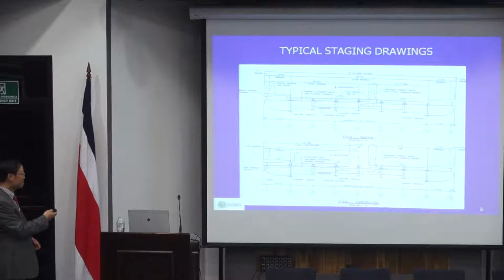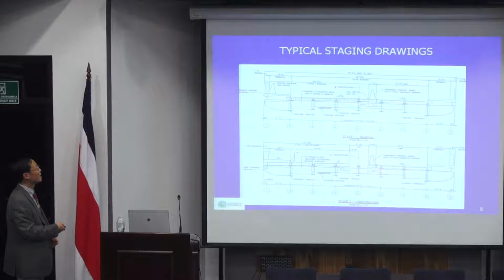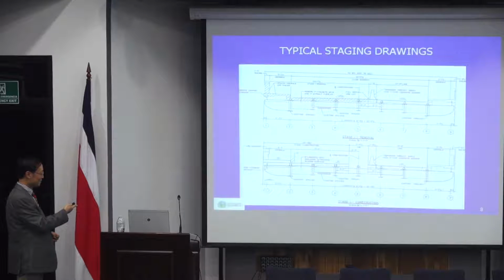And this example is a staged construction. This bridge has staged construction to maintain one lane of traffic and one sidewalk. Once they cut there, you need to make sure that the cantilever is working. And of course, when you have vehicles here, before the load was shared by many girders, now it will be different. So that girder may carry a lot more live load than otherwise.